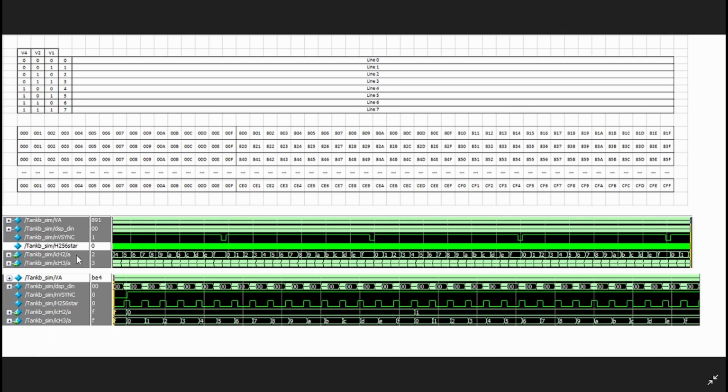So effectively, as I said before, we've got our most significant byte, not bit, and least significant byte. And when the VSync finishes, it goes high, we start counting with our most significant byte, and that counts 0 to F, and then I've zoomed in on the bottom here, and so the least significant byte also goes 0 to F for every single one of the other higher most significant bytes. So therefore we get a count from 0, 0 up to FF. So that's what that counter is doing.